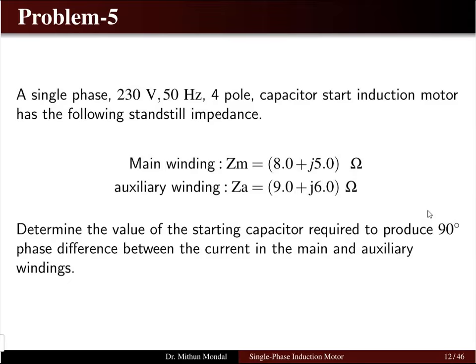Problem number 5, again we discuss single phase. The single-phase ratings are given as 230 volt, 50 hertz and 4 pole. This is started by the capacitor start method. We have discussed many categories of induction motor starting. 3-phase induction motors are self-starting, while the single-phase induction motor does not start on its own. You require some different starting techniques, usually using a capacitor.